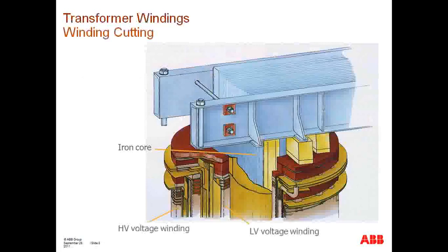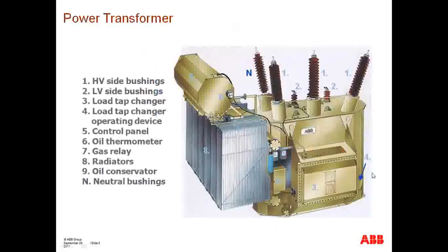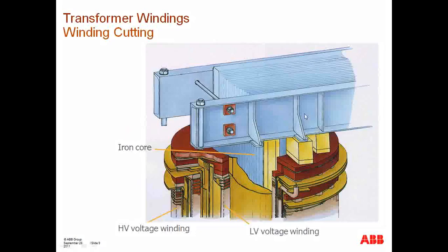Now, this is a view of the core inside of the transformer, or what's actually inside this metal enclosure. And what you're going to find is the following. You have a metal structure, okay, with several layers. This is the core, and the core is laminated to reduce or minimize the amount of eddy currents, the amount of losses, from a transformer design perspective. Okay, and then you could have multiple legs inside the core design. I think I have a couple of pictures moving forward that provide a good visual on that.